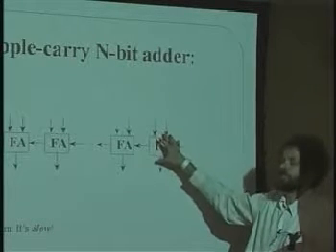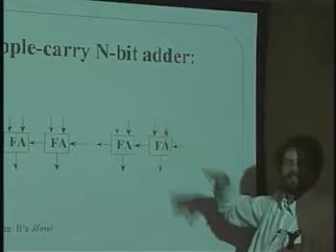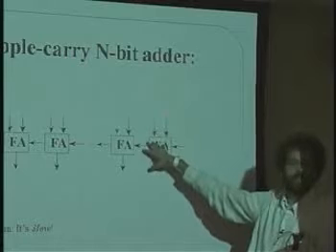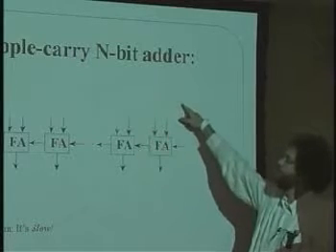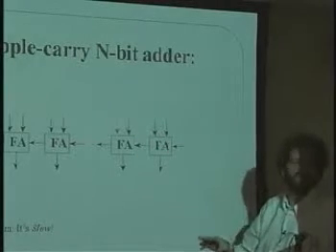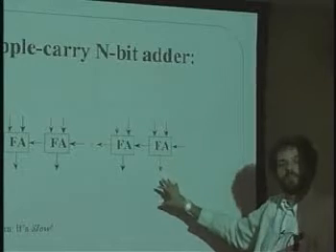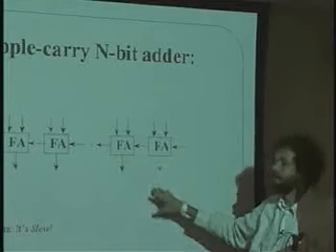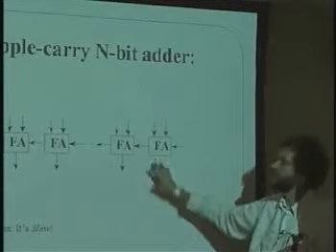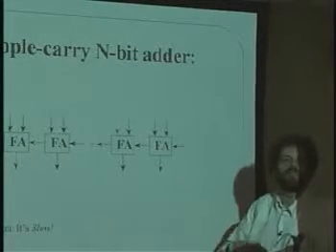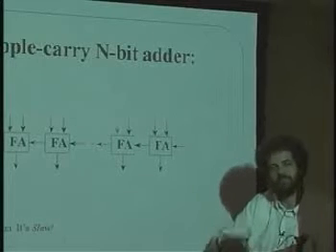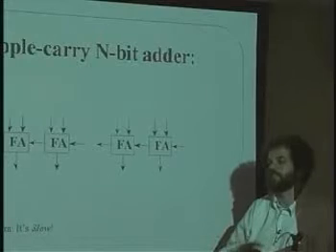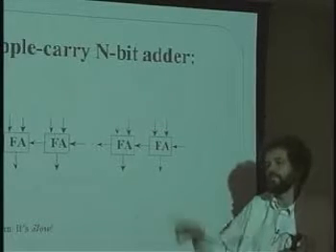You can actually build a system with no clock at all. I'm giving a little hint here: they're called self-timed systems, where in addition to the data that goes into an ALU like this, you have a start pulse that says, okay, go. And what comes out of the ALU is not only the answer, but a finish pulse saying, I'm done. As soon as that's done, the next piece of circuitry that depends on the data is triggered, saying, okay, you start. These little start pulses chase each other through the circuit and loop back and start all over. The system has no clock at all other than these start pulses going around and around.